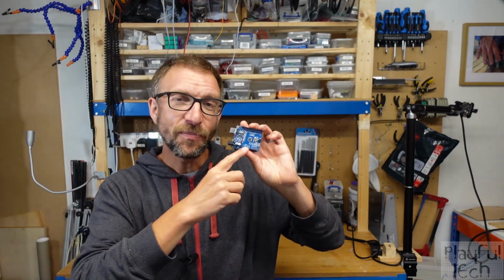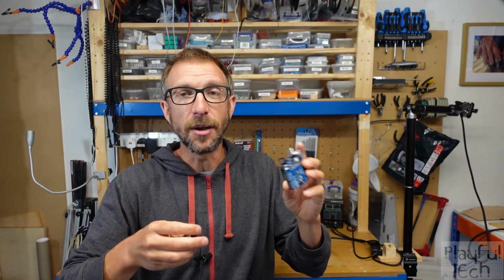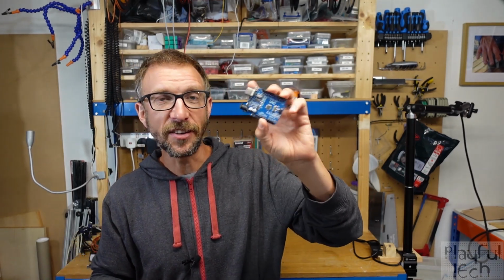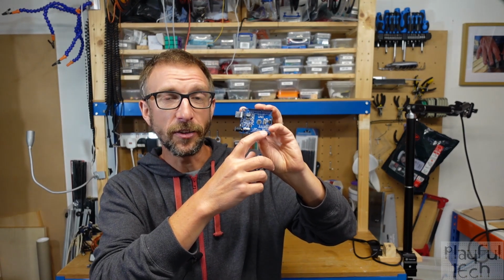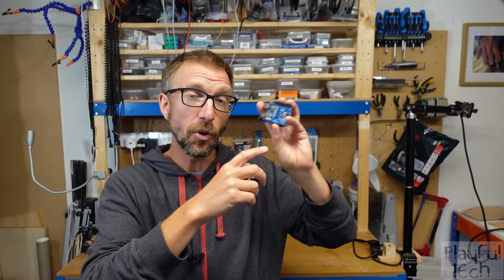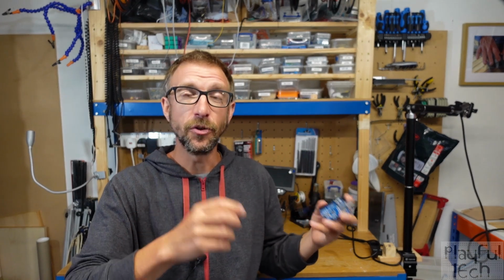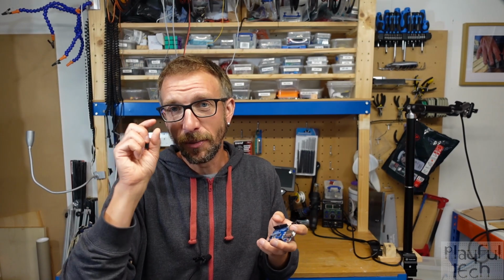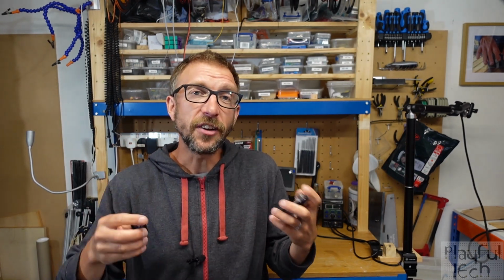Now, the ADC reads the voltage at the specified GPIO pin and converts it to a number. But the resolution of that number varies. An Arduino has a 10-bit ADC, so it can represent the voltage at one of the analog pins with a value between 0 and 1023. An ESP32 has a 12-bit ADC, so it maps the voltage to a value between 0 and 4095. It's got a higher detail of resolution. And then you can use that digital value in your code however you want.